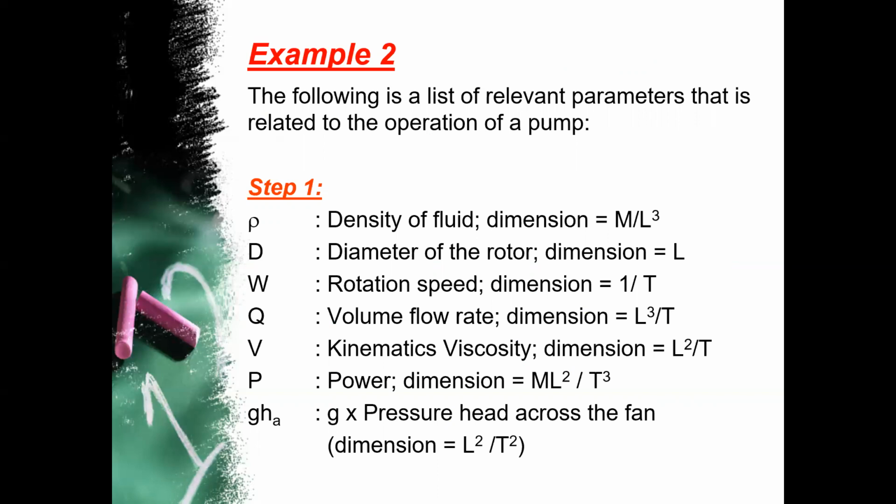For Buckingham pi, the trick is actually through reference variables. You need to select the reference variables. Usually the number is equal to 3 because we always use MLT, mass, length, time. Then we rearrange that and put it back into the remaining variables. So that's basically how to do the Buckingham pi.